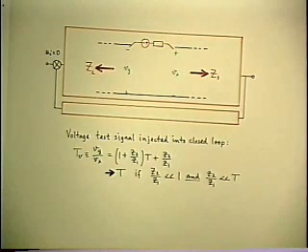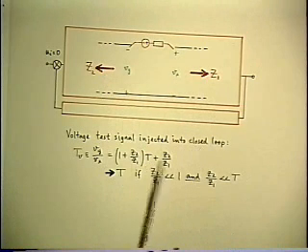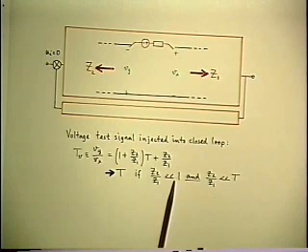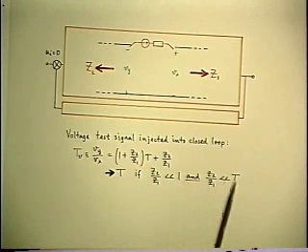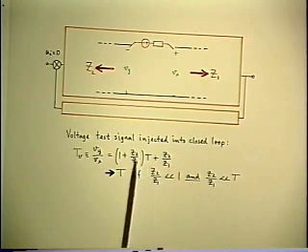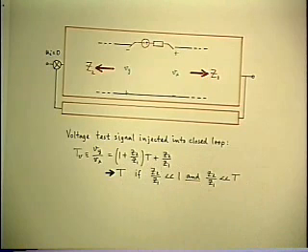But notice now what those conditions are. Z2 over Z1 has to satisfy two inequalities. The ratio has to be much less than 1, but it also has to be much less than T itself, because you have to be able to drop that ratio from two different places in the equation. Now notice at different parts of the frequency range, one or the other inequality becomes dominant.